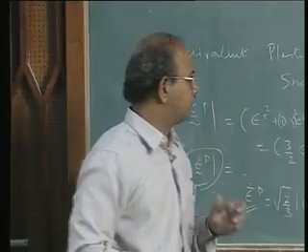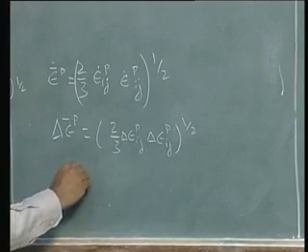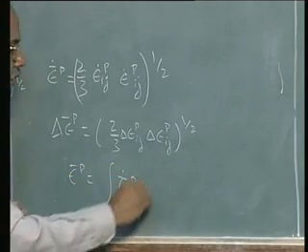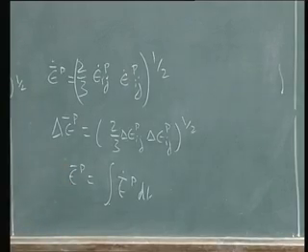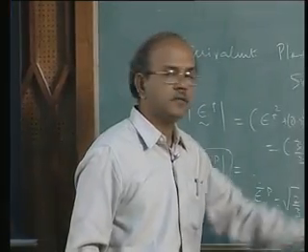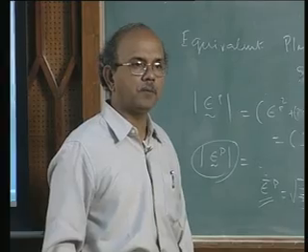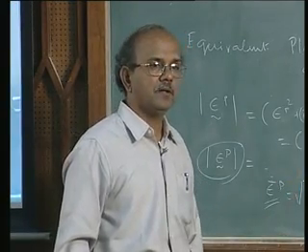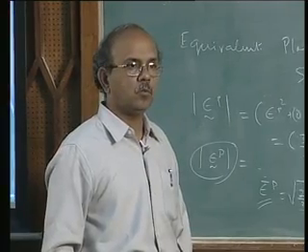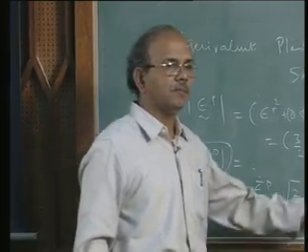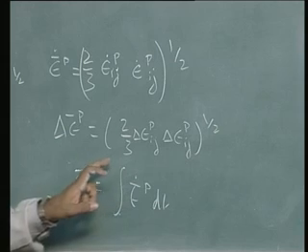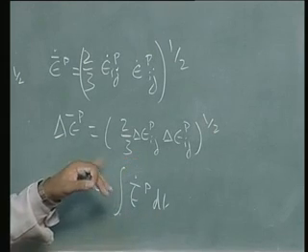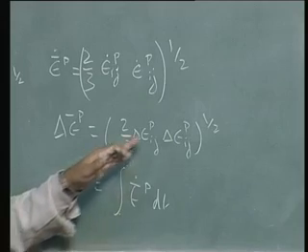Strictly speaking, epsilon bar p should be written as the integral of epsilon bar dot p dt with time, or the sum of delta epsilon bar p's. Note the difference between this and the Mises stress. What is Mises stress? Mises stress had, in this case, 3 by 2 S ij. Now we have 2 by 3 delta epsilon ij p, delta epsilon ij p.